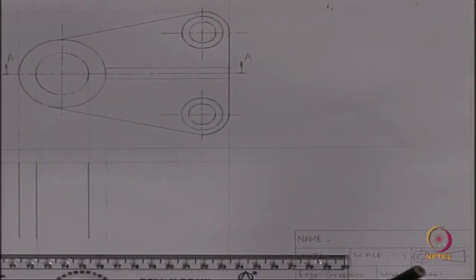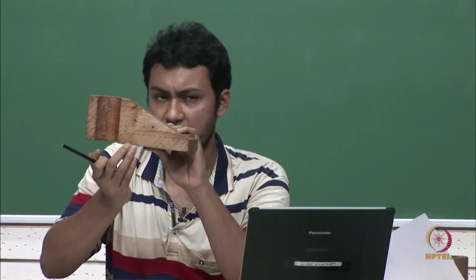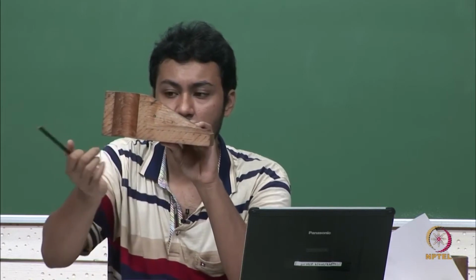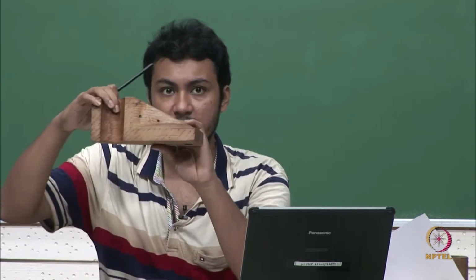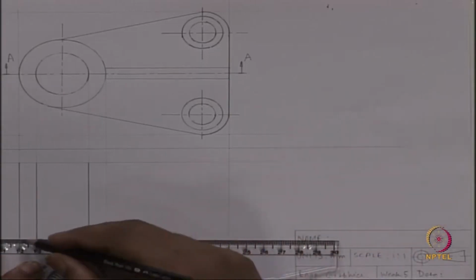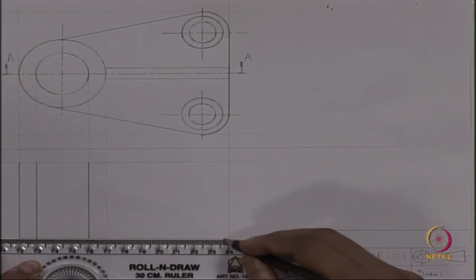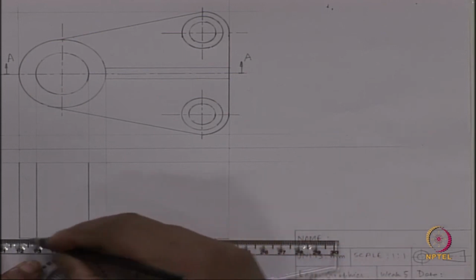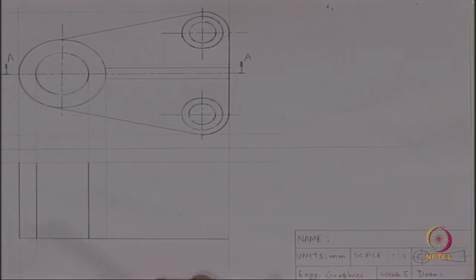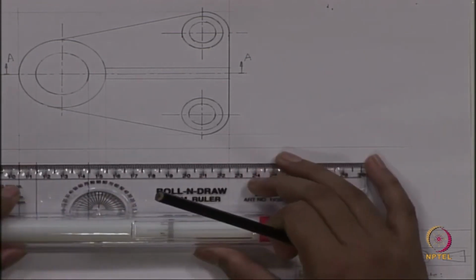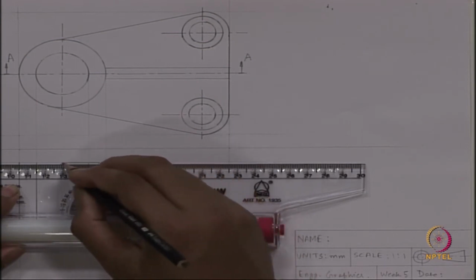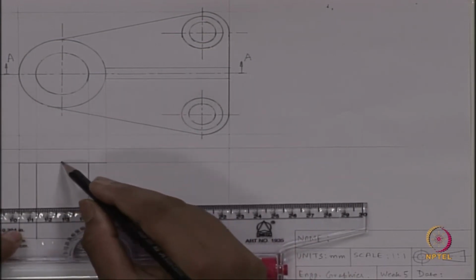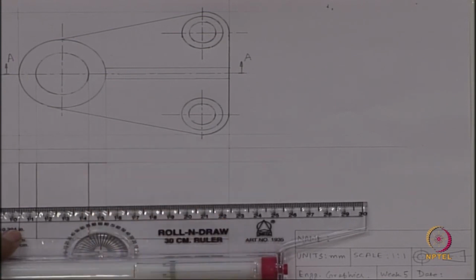And the whole lower part, this line, this curved line, and this whole line, if we look from the front, we will see a single line instead of all these, and that has a length of 120. The top line also has to be joined. We won't see any curved line here, instead we will see only a single line. This line was actually curved in the 3D figure, but we will look at a single line only.